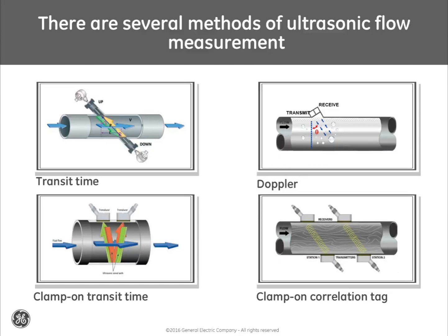It is a natural property of any fluid and is mostly a function of temperature. By knowing the fluid, the installation accuracy can be validated with sound speed. Also, an ultrasonic meter can track and trend a fluid's sound speed for changes in process conditions or process media.